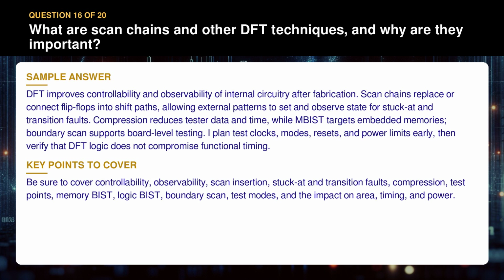Be sure to cover controllability, observability, scan insertion, stuck-at and transition faults, compression, test points, memory BIST, logic BIST, boundary scan, test modes, and the impact on area, timing, and power.